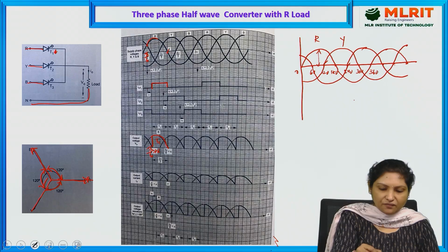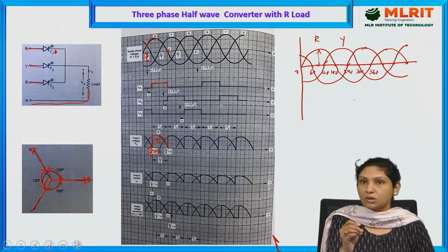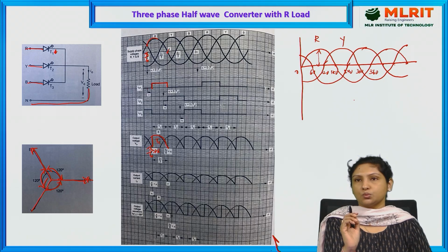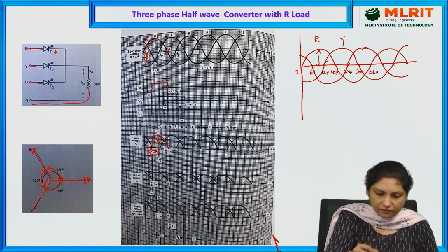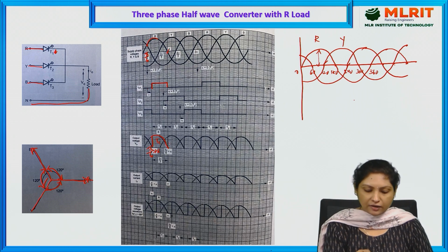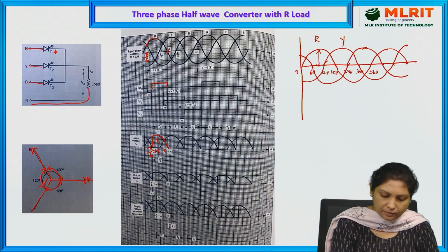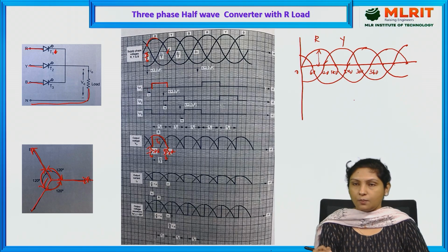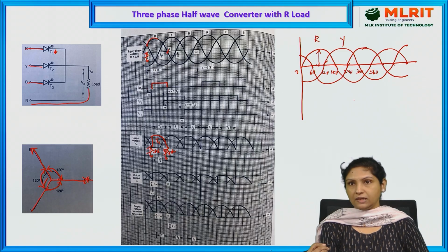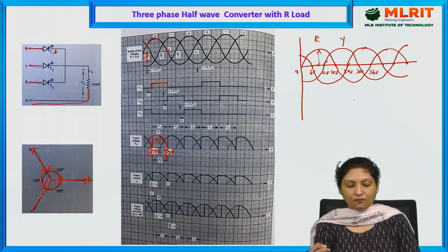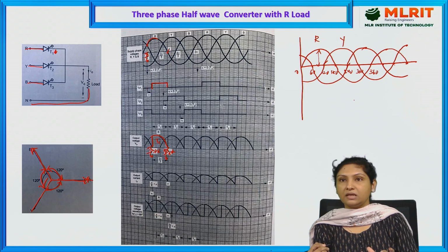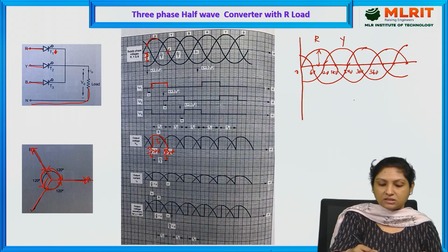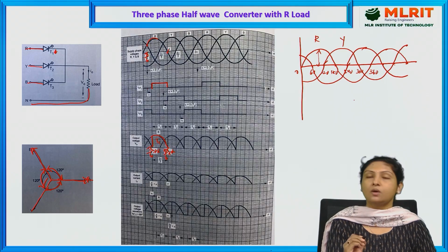And if you see, Y phase has appeared, but thyristor 2 doesn't conduct because we are not providing any triggering pulse for thyristor 2. So that is the reason. I am calling this instant pi, and I have written this as 5 pi by 6 plus alpha. Why is it so? Pi by 6 is 180 by 6, which is 30, and 30 into 5 is 150. 150 plus alpha, which we have taken as 30 degrees, is equal to 180 degrees. So the thyristor will be conducting till this instant called 180 degrees.